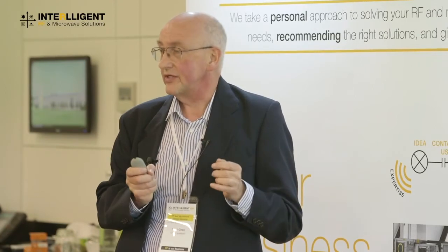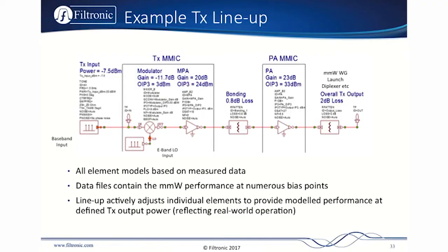One important point I want to make is that at these frequencies, I don't know whether we've got any component manufacturers here, but you can't trust the data that you find on the data sheets. They give you simple things like OIP3 and PSAT. It's pretty much meaningless if you want to design a real transceiver. So we characterize all of the chips ourselves, measure them on wafer, and build up, putting real measured data into a VSS or similar model. And then we can look at the contributions to linearity as you go through the chain.